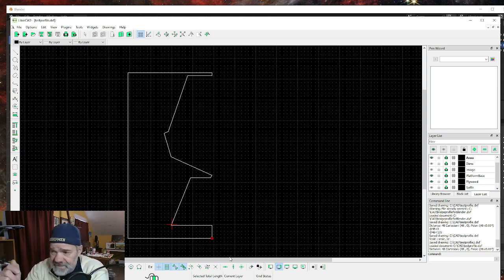Now, if you're doing millimeters, you'll need to convert to millimeters in Blender. You'll need to drop some zeros, add some zeros, whatever it takes to get it. But for Imperial workers, you need to convert that measurement, so when you bring it into Blender, it reads meters. I'll show you.